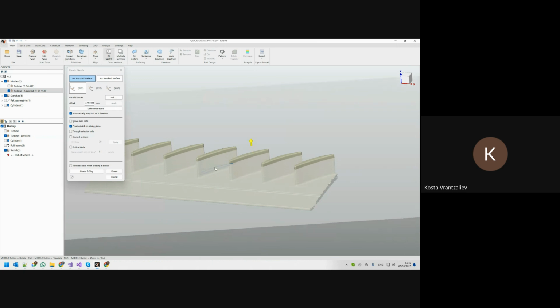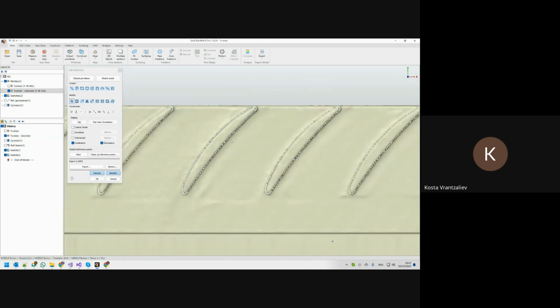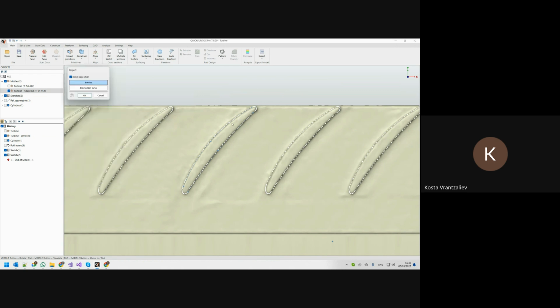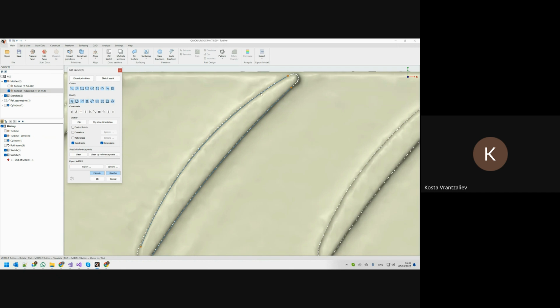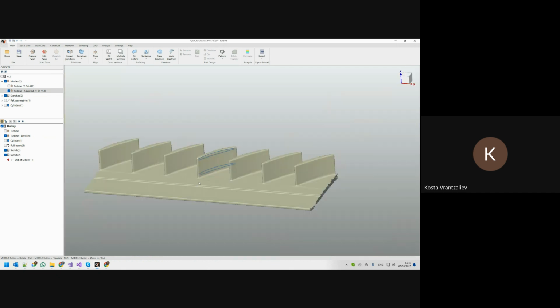We'll use the opportunity to show, because you have two, like Victor showed for later for this lofting, we need to make another one here on top. In this case, I'm going to use what is called project the others. I can just pick the others from the other sketches. The reason is that in this case, I don't want to follow the shape, but I want this to be perfectly on top of each other.